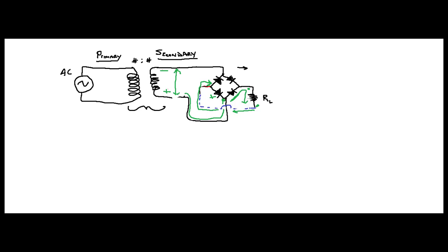Depending on what your resistance is and current. Now, that voltage is what's at this point. So look, your voltage here is higher than it is here, so this is reverse bias. So obviously we cannot go that way. The only way we can go is this way. Now, you're at another junction. Where are you going to go?